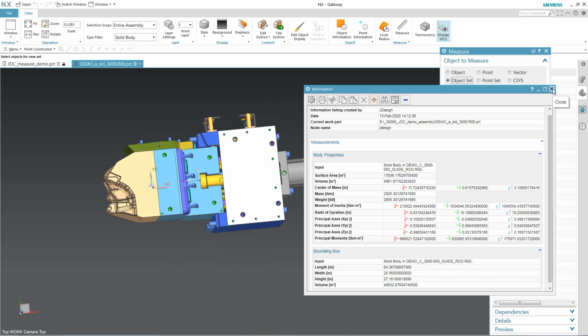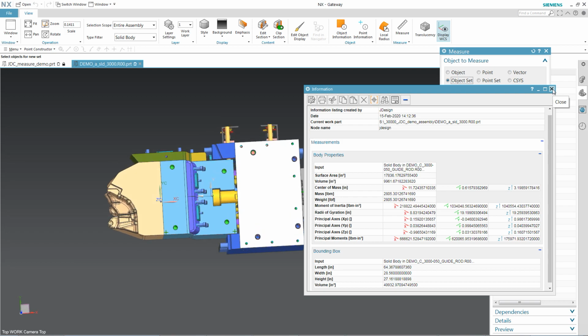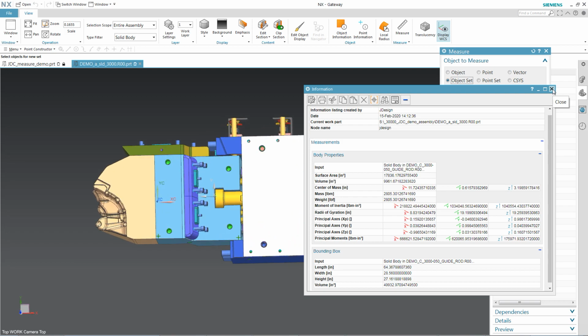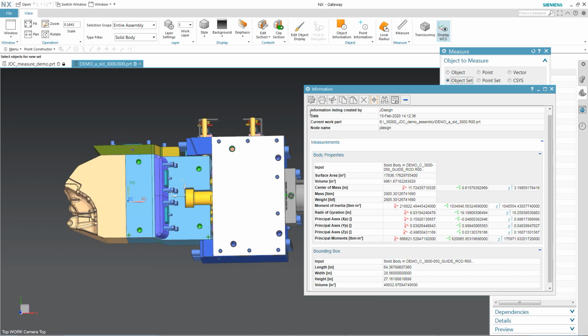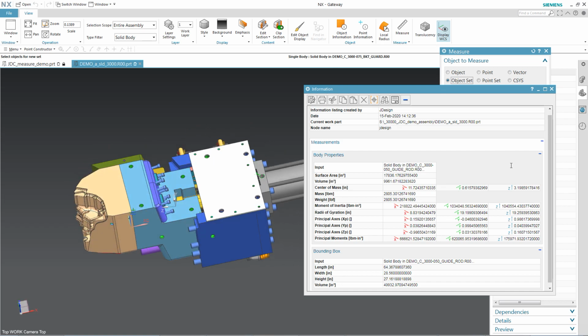If I wanted to put a lift hole in to lift it up in this direction, I would need to either put it right where the centroid is, or put multiple lift holes in where that would become the centroid, which I'm looking at now. I can see I would have to put an eye bolt there, an eye bolt there, and maybe one here and one here, and I could lift the whole thing and it would be balanced for lifting.